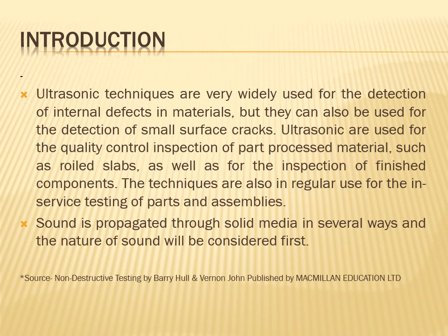Ultrasonic techniques are widely used for the detection of internal defects in materials, but they can also be used for the detection of small surface cracks. Ultrasonics are used for the quality control inspection of part-processed materials such as rolled slabs, as well as for the inspection of finished components. The techniques are also in regular use for in-service testing of parts and assemblies. Sound is propagated through solids in several ways, and the nature of sound will be considered first.